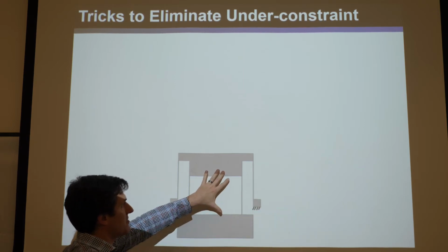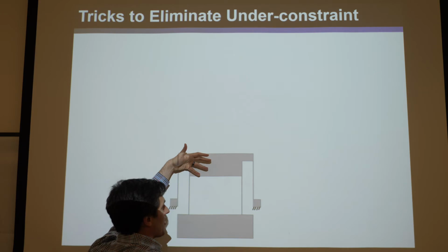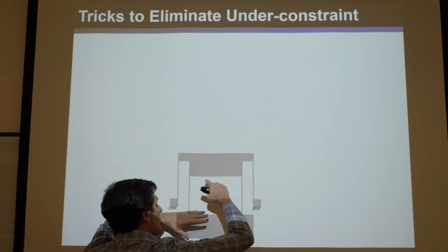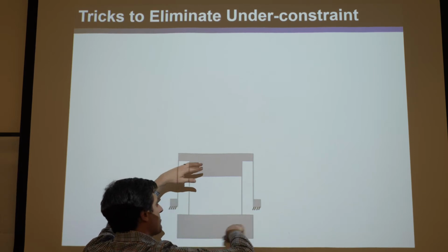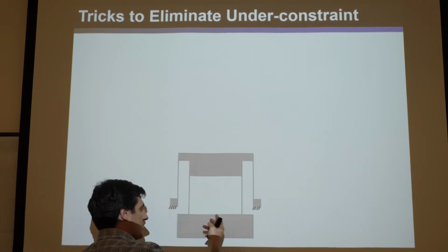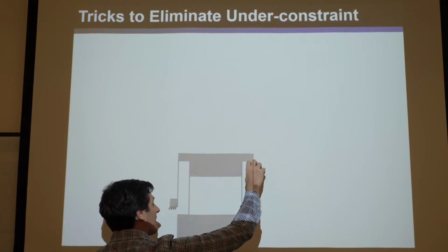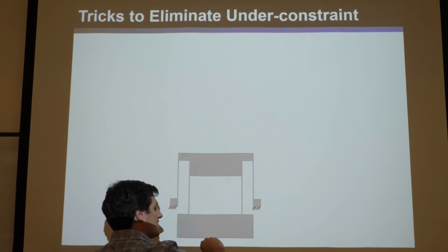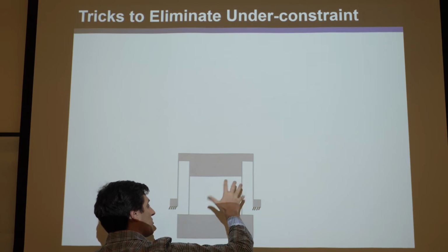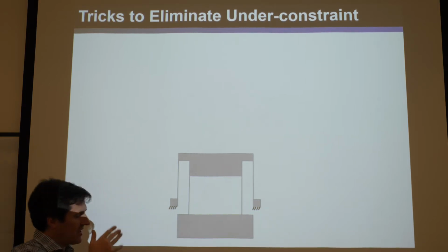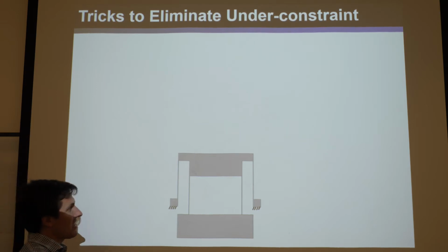There's nothing forcing this to be 2 to 1. As a consequence, if you force this to go 1 and this to go 2, they will cancel out the arcing parasitic motions, and this will go twice as far. But if you actually push, this will try and snap back because of the stiffness, and it won't achieve a 2 to 1 ratio. It won't do it, and you'll still get some parasitic error.